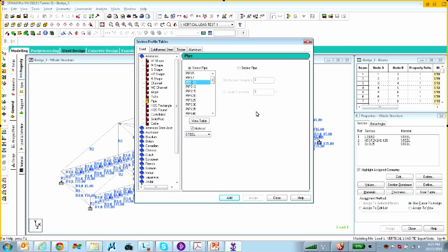Because I noticed I would define very skinny pipes sometimes, and it would just go ahead and give me 0 for inertia values, IX, IY, IZ. After a certain diameter, it just went to 0. So I guess that is slightly conservative, but I just didn't know if it was really set up to do code checks with such small members.